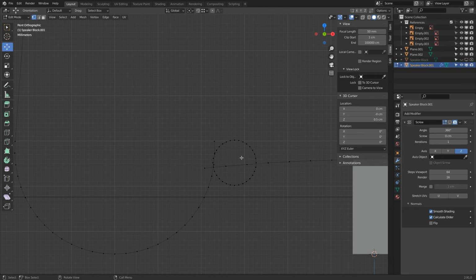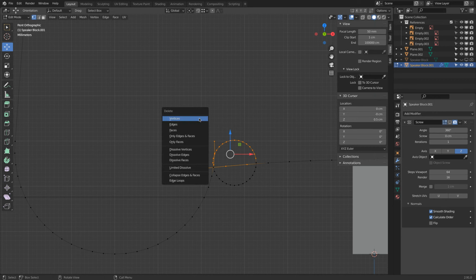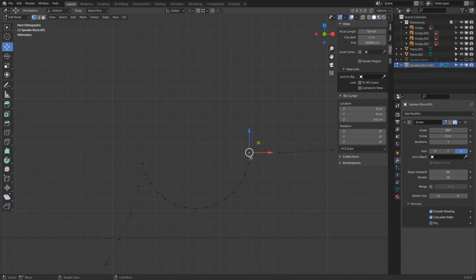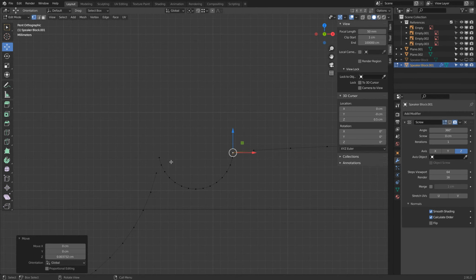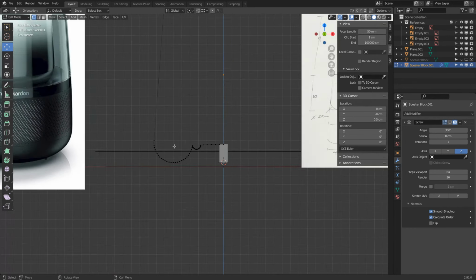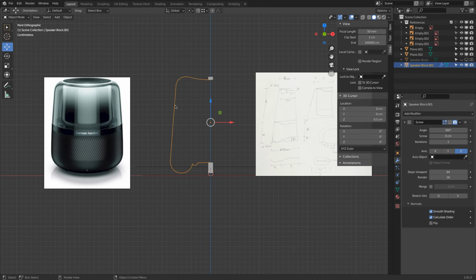And in this exercise, I'm showing you how simply via polygon models, we very quickly block out all the stuff we need. So all this we X and delete, and then G G, we slide this down a little bit more and then connect these two, or bring this a tick up. And then here, U and U, F, we just fill it. Cool. Okay, so let's see how this looks.